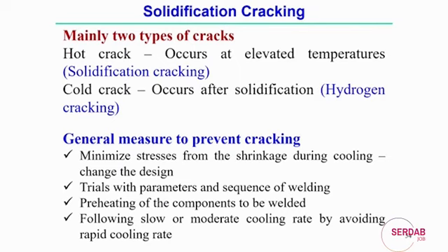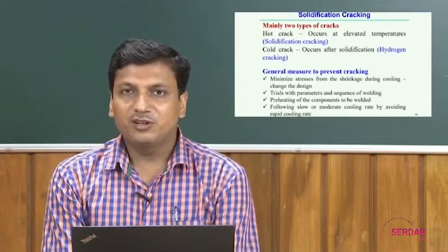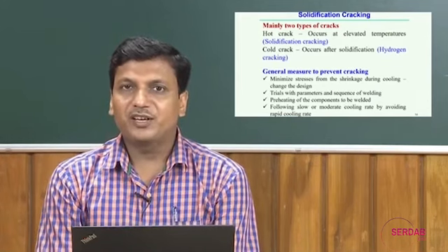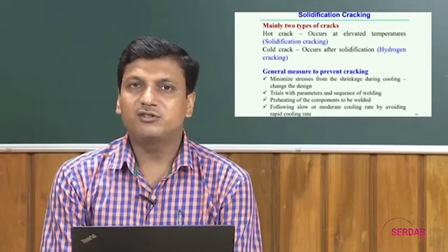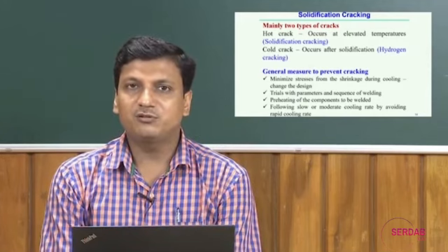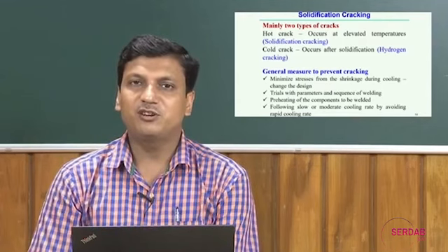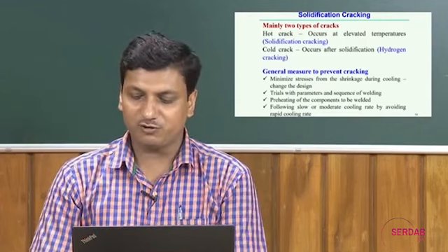And finally, how to prevent solidification cracking: by following a very slow cooling rate, or even a moderate cooling rate, by avoiding a rapid cooling rate during the solidification process. That can be one of the measures we can take to prevent solidification cracking, or in general the cracking phenomena observed during the solidification process.